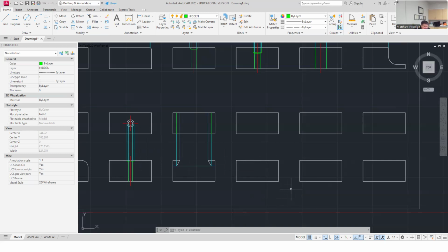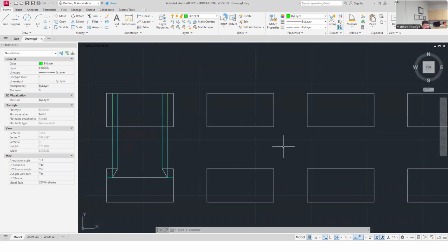So when machinists mill stuff out, they use bits that are made to cut on the side, whereas with the drill bits we're used to, the point does all the cutting and the flutes on the sides can't really cut. You can't take a drill bit and ram it in on the side and start cutting something, but machinists can. They have end mill bits that will cut on the sides and create a kerf loss, cutting through something. So I feel like this is maybe a machining tool that's cut through. Of course, what I explain without pictures doesn't really make a lot of sense.